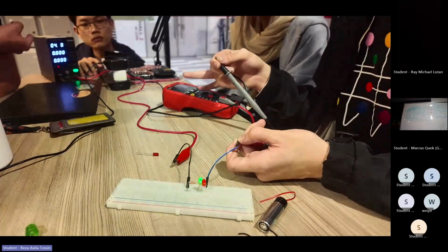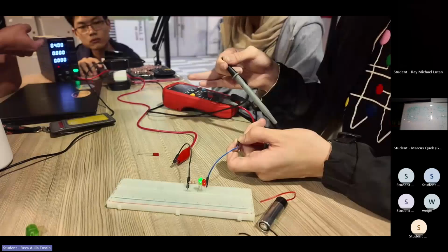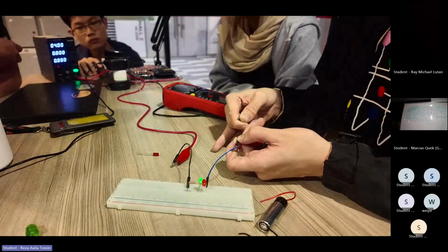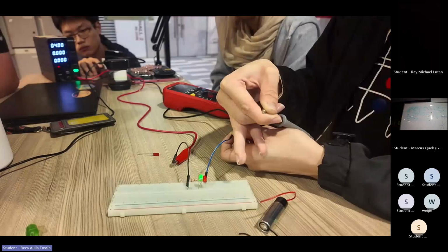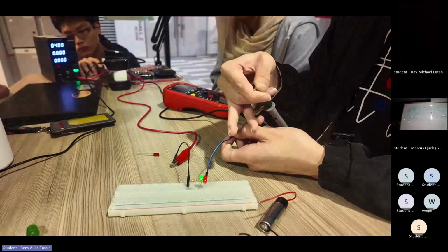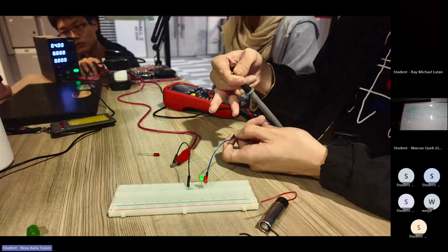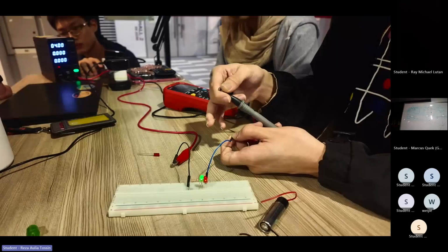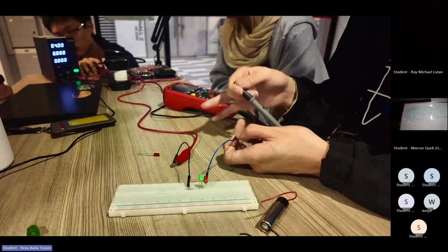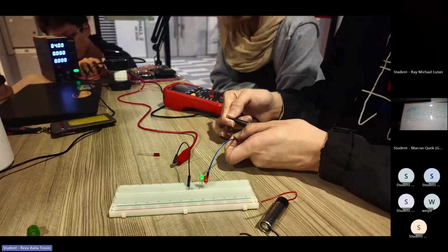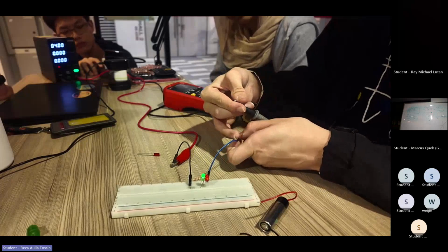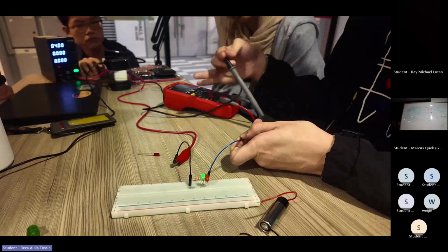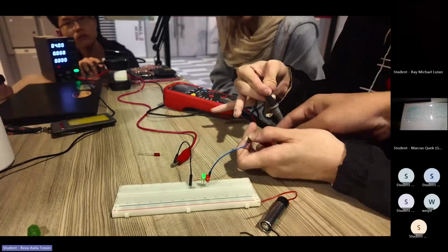So you can see as we approach the forward voltage, which as we calculate, there are 2 diodes in series, so it's 1.7 plus 2.1, which is 3.8. Right now the amperage is very small. Why? Because there's 0.2 volts across that resistor, and the resistor is 2.2K. So you can calculate.